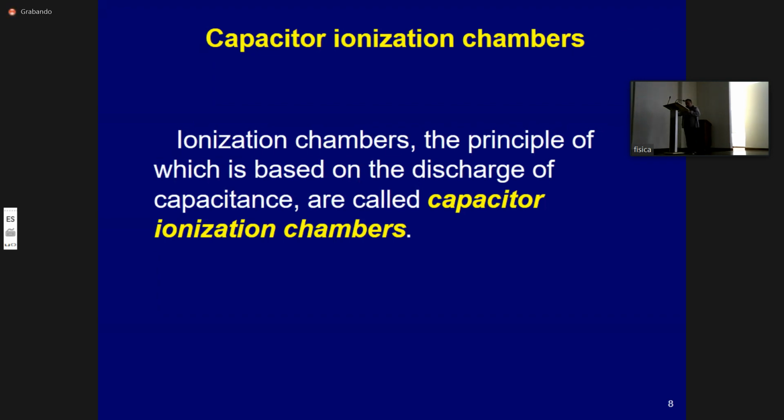The recharge of such dosimeters is carried out from a separate voltage source. The potential difference or the charge accumulated on the electrodes after irradiation is determined either on a separate measuring console or using a special electrometer mounted in the body of the dosimeter panel.